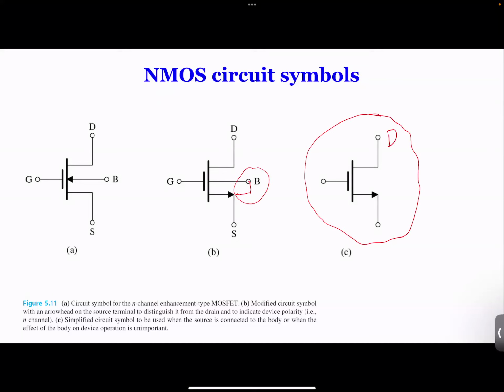So on this diagram, you have drain, you have source, then you have gate, and you can see the current direction is flowing from drain through the MOSFET and out of source. So this is what we're going to use. The relationship between the current from drain to source, which is called ID, and the voltage across drain and source, which we call VDS, and also the voltage across gate and source, which we call VGS.